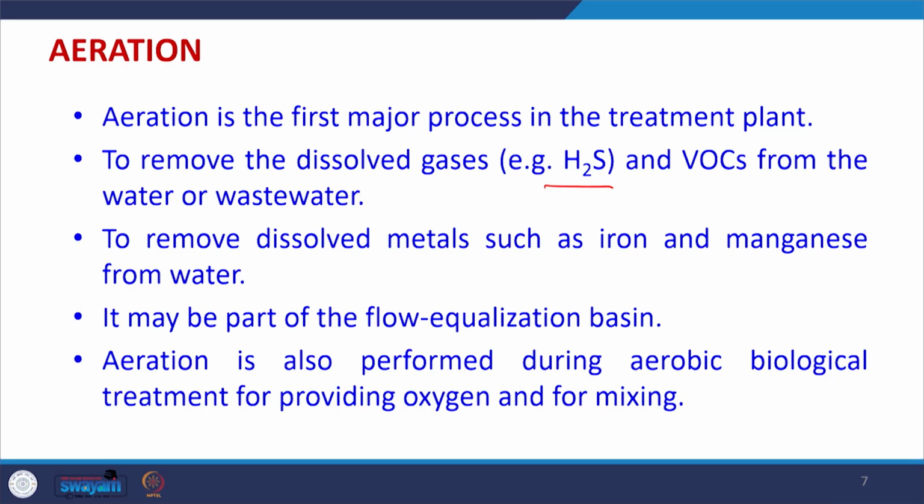Also, it is possible that aeration can be performed in the flow equalization basin itself using various aeration methods. So, aeration can be done in the flow equalization basin itself, or aeration may be done in a secondary step.